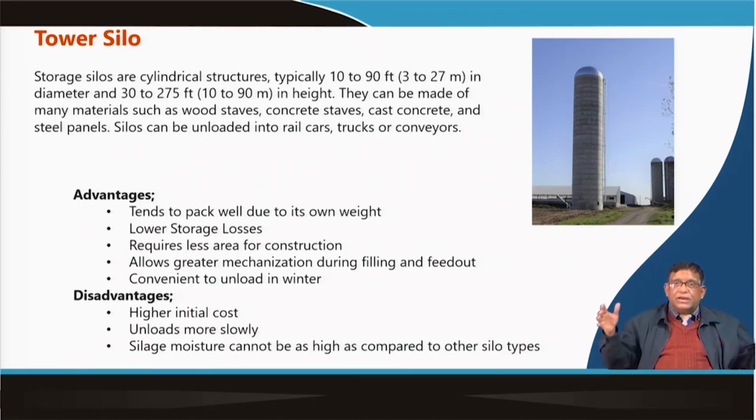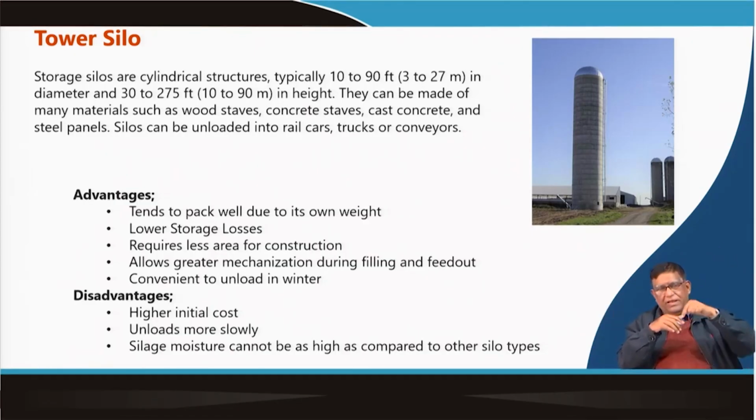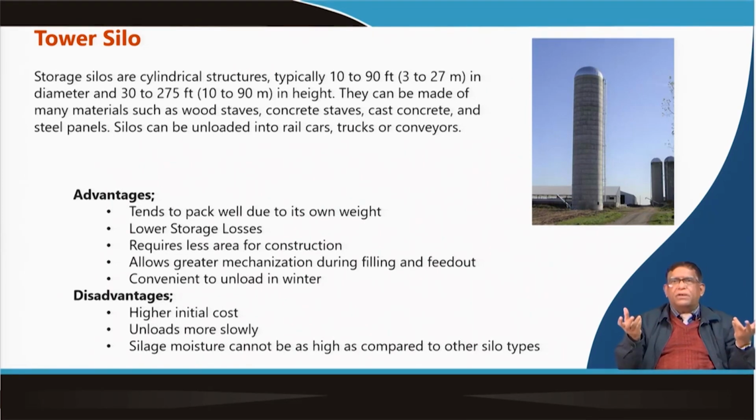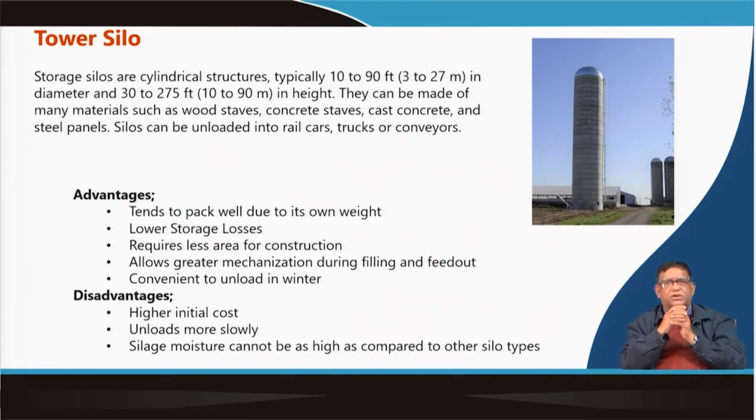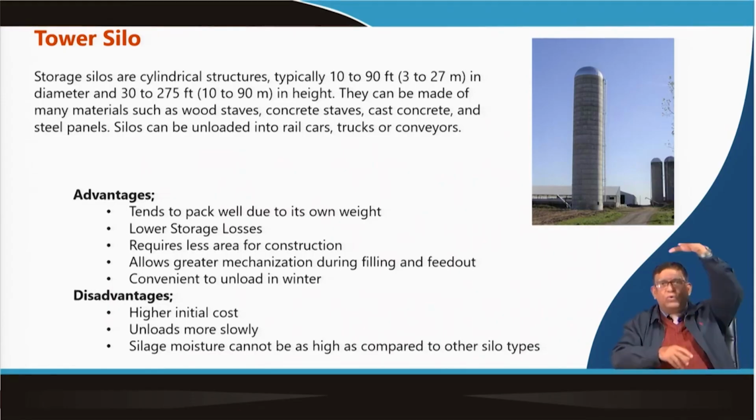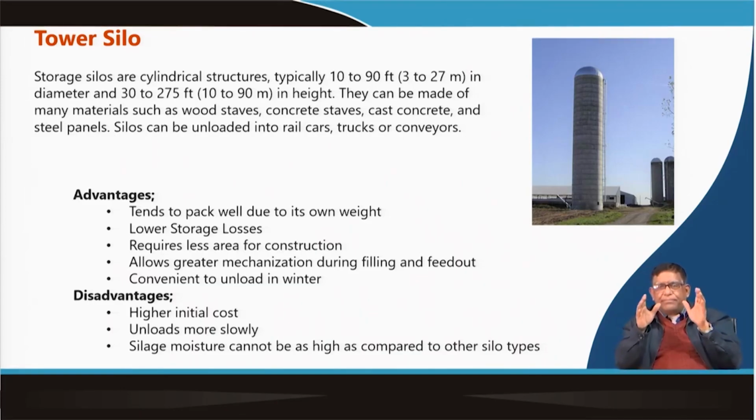So, in a very large silo you should see how it is being filled. While you are filling, if you allow the whole material to come from the top, if it is coal, then the whole coal will get shattered. There will be a lot of pulverization and powder will be formed, and slowly it will be a situation of coal dust explosion. So, in such cases, the coal will not be dropped from the very top to get pulverized. You can stack it, and accordingly other arrangements can be done.